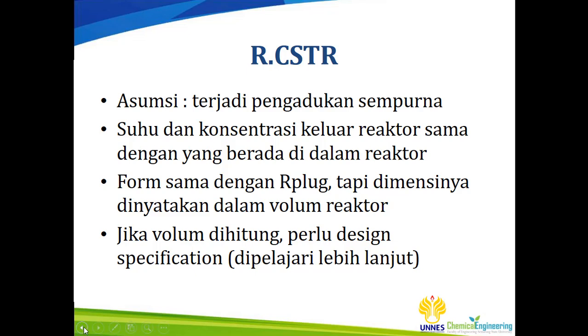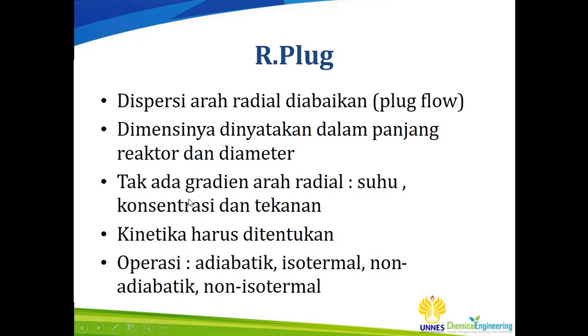So the input parameters for CSTR and R plug are the same. The difference is only the dimension of the reactor. In a CSTR, you have to specify the volume of the reactor, while for the R plug, you have to specify the length of the reactor. The operation can be adiabatic, isothermal, non-adiabatic, or non-isothermal.